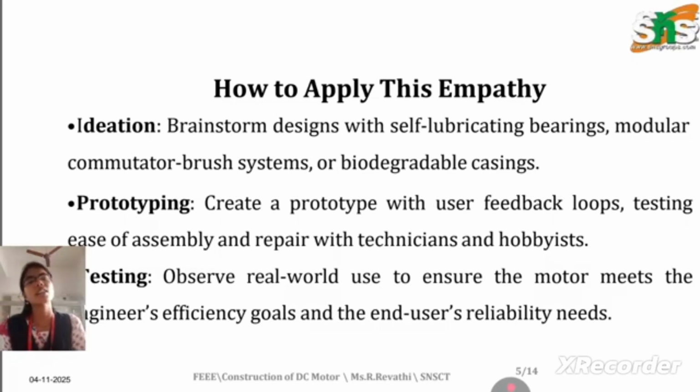So we know that construction of a DC motor is the same as the construction of a DC generator. There is a single construction which is the basis for both, common for both the DC motor and DC generator. The only difference is the working principle of the machine, that is, the application of a certain law that varies the process. If Faraday's law of electromagnetic induction is applicable, the machine operates as a DC generator, whereas when Lenz's law, Faraday's law and Fleming's left-hand rule are employed, the machine acts as a motor.